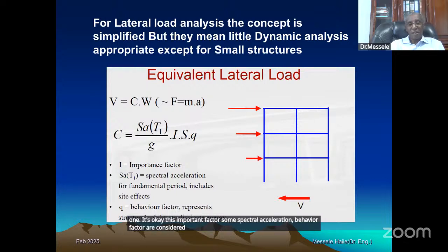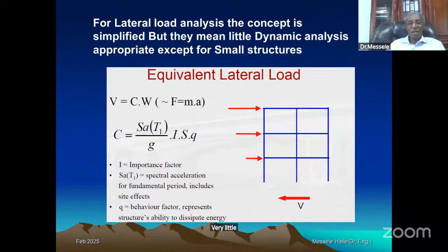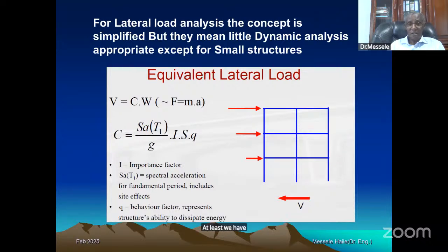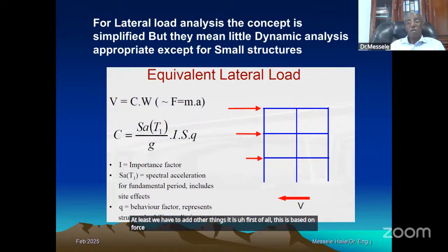But truly speaking, just in one word, maybe we can raise it in the discussion, very little is done to save buildings using the equivalent lateral load used in codes. At least we have to add other things. First of all, this is based on force. Earthquake is an energy. It is not a force.